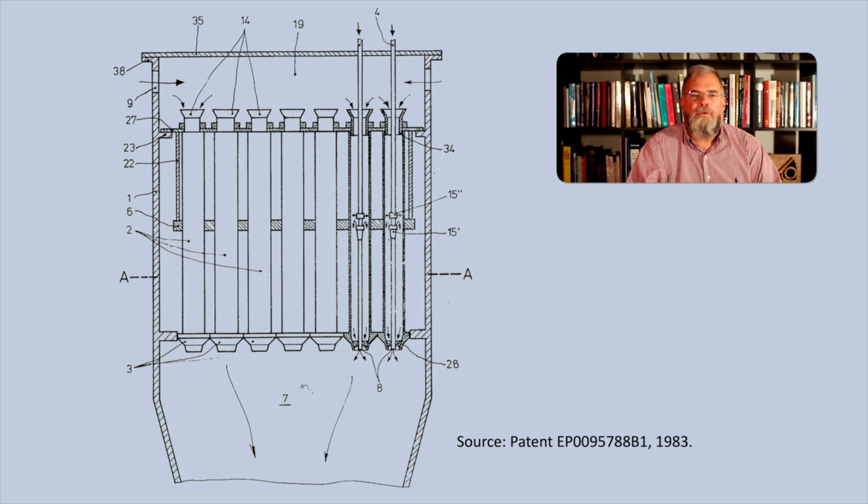The world's first premix burner for a gas turbine engine was developed by Brown-Boveri, or BBC. This went into service in 1984 on a GT13 engine in Dusseldorf, Germany. This was a relatively simple design consisting of a long duct in which fuel and air were premixed prior to encountering a swirler at the exit of the duct. Additionally, to avoid flashback, a nozzle was added to the outlet of the duct to accelerate the flow.